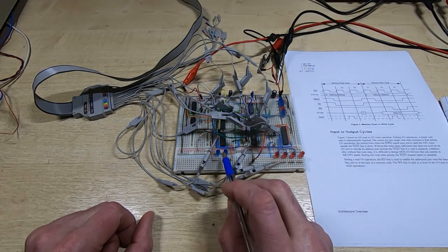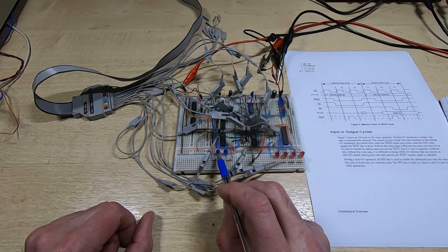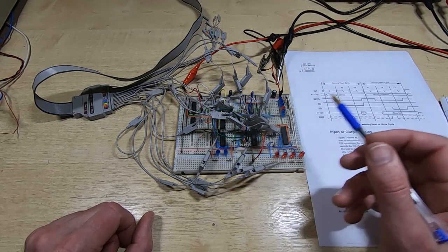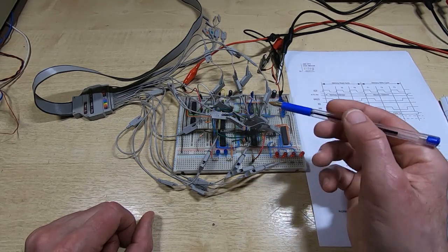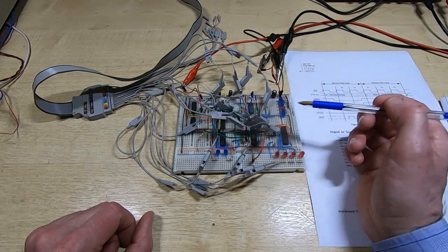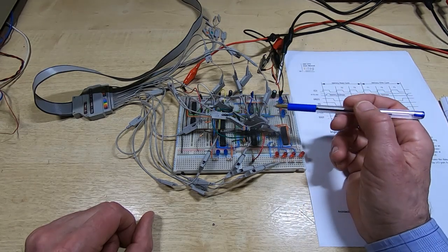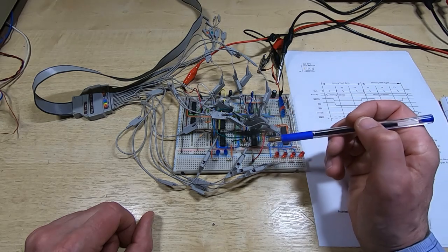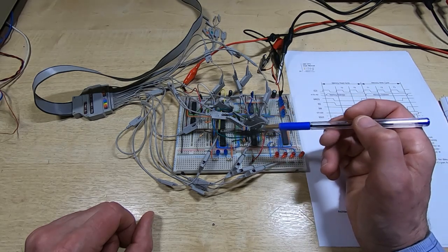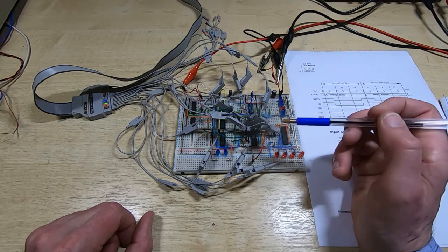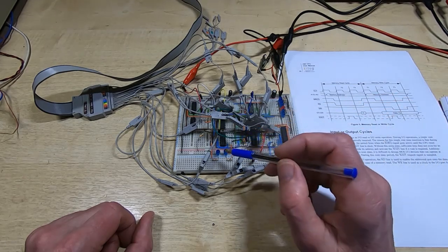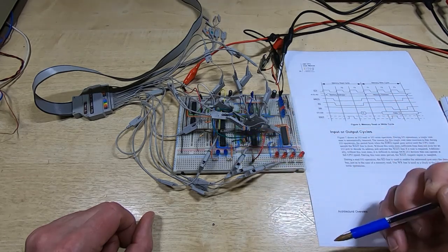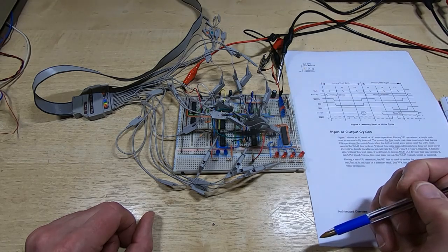The two LEDs on the left here are the address 0 and address 1 lines that go through to the floppy drive controller. And again, we have to force those high when the DMA system comes into operation, because the data register in the floppy drive controller is at address 11. So these two LEDs should come on in DMA mode.